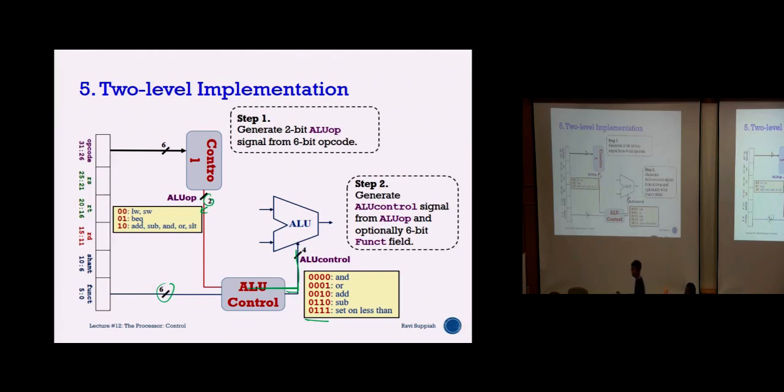When you have an ALU, for example, let's say we're trying to do an AND operation, and somehow the 2 inputs for the ALU arrive before the ALU control is done generating the AND. How does the ALU know this is not the input I want? I need to wait a bit. Like, this is not going to be an AND operation, right? Because it's going to receive 0, 0, 0, 0. Right. So basically, all of that is part of the internal microprocessor timing, so it can time every single substage. But I thought that's only for pipeline processors.